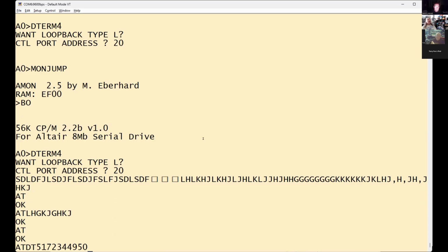That's Intel hex. It's the format of the file. It always starts with a colon. The next number is going to be either a 0, a 1, or a 2, which means it's either sending you 8 bytes, 16, or 32 bytes. And then there's, I think, two more zeros, and that tells you something about the file type. And then the address will be the next 4 characters. And then the next thing that happens is you start your code.